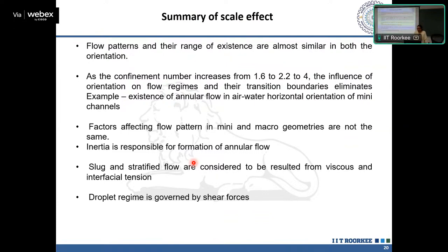So, in summary, the factors affecting mini and micro channels are not the same. What we observe is that inertia is responsible for the formation of annular flow. Slug flow, not stratification, mostly results from viscous and interfacial tension forces, and the droplet regime is governed mostly by shear forces.